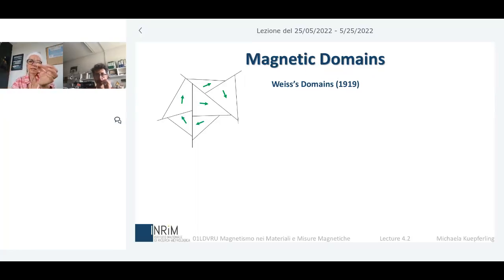But it's not like that, because we have magnetic domains, and the magnetic domains will orient in different directions, and overall magnetization might be quite small. When we bring it in the magnetic field of our permanent magnet here, so it would be also sufficient, of course, to keep it just close, then these magnetic domains will orient along the field lines of the permanent magnet, and then they become something like a permanent magnet.